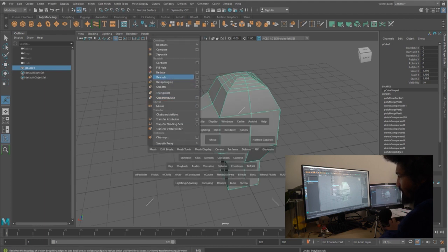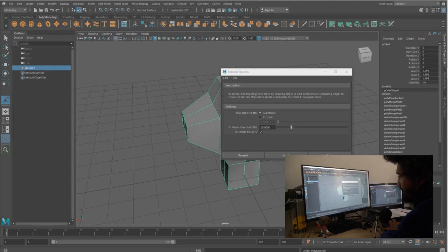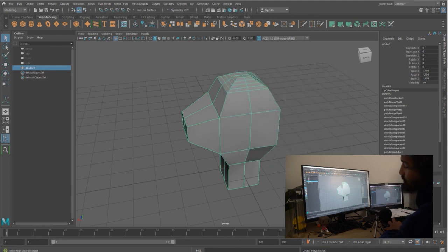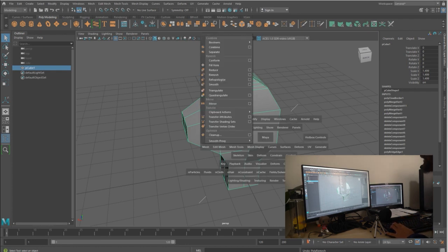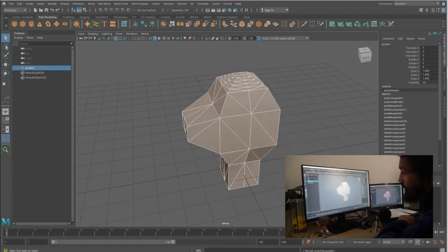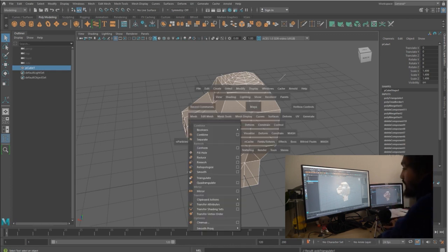We can maybe do a remesh here and say, oh, we want 20% more, 20% less. This is what we may use in the future to optimize geometry. On the mesh side as well, you have the triangulate and quadrangulate. That's when you want the software to try its best to go from quadrangulate to triangle, or from triangle to quadrangulate. For triangle it's very easy because it's just gonna split every face in two. But for the quadrangulate, it's gonna be a bit harder.